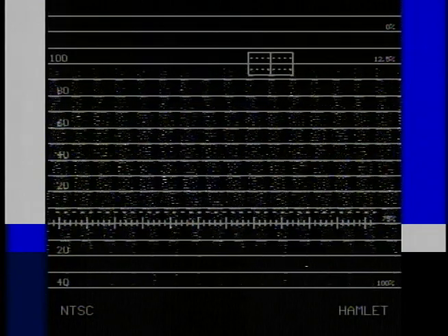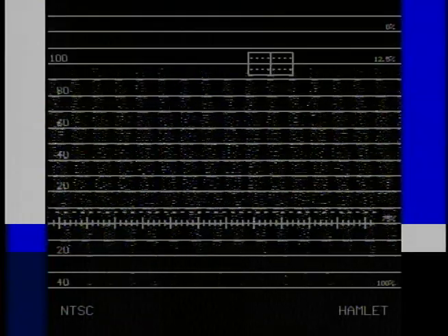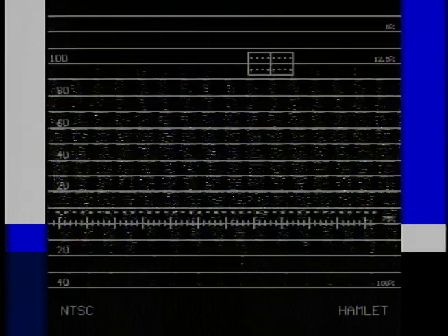The scanning process. An NTSC video signal is a scanning process that sweeps out a series of horizontal lines from left to right. The electron beam scans the odd-numbered lines first, then it jumps back to the top of the screen and scans the even-numbered lines. The scanning of all odd-numbered lines takes 1/60th of a second and is called field 1.